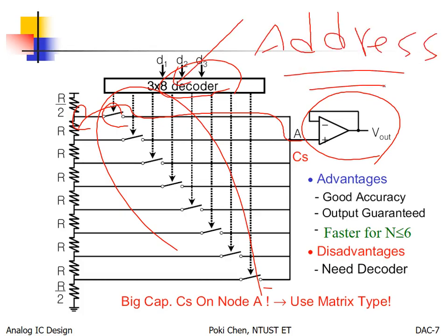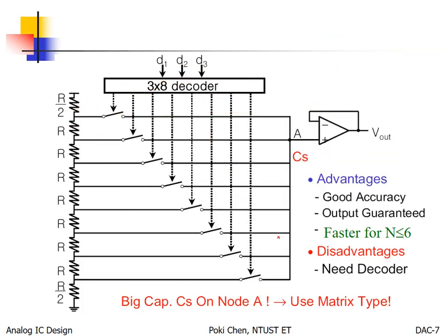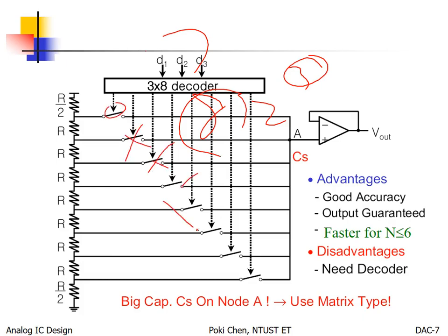That is in digital logic, a decoder. That's it. So for example, you have a 3-bit input. You will have 2 to the third power, right? You have 8 outputs, and only one will be on. Others will be off. That is the function of an address decoder.